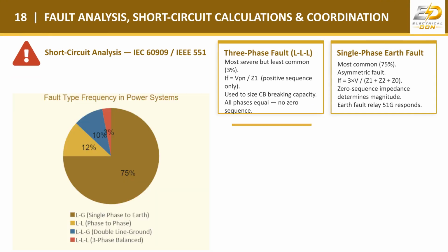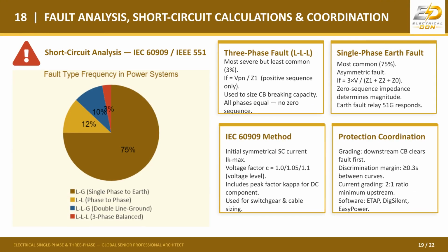Fault analysis is dominated by the common single-phase earth fault. Three-phase faults, though rare, determine circuit breaker capacity. Protection coordination uses grading methods to ensure selective fault clearance, often modeled with specialized software.